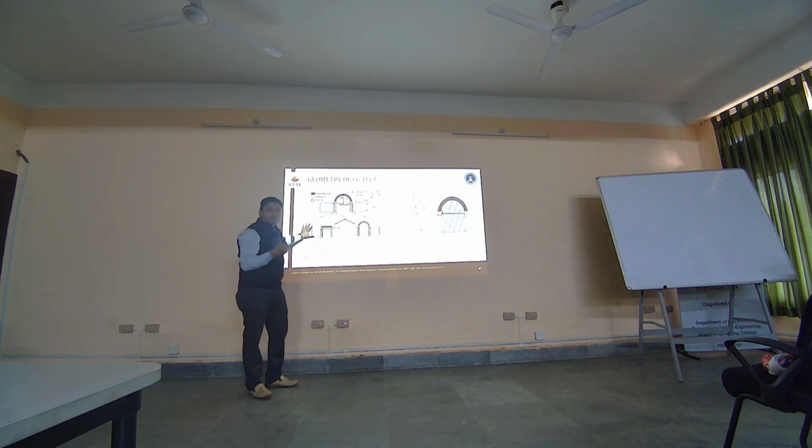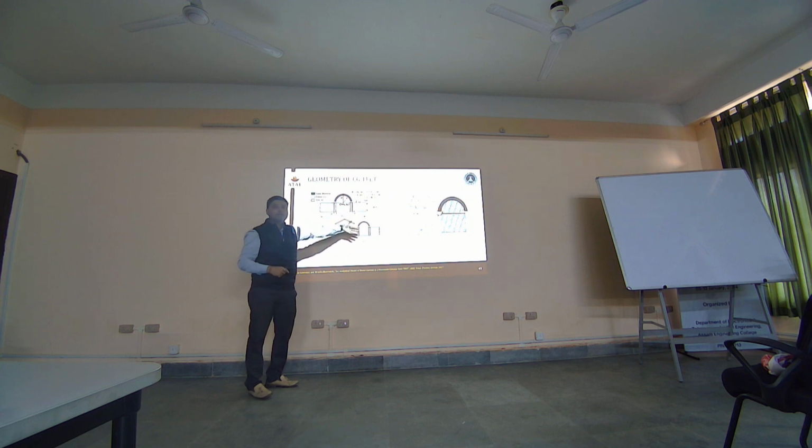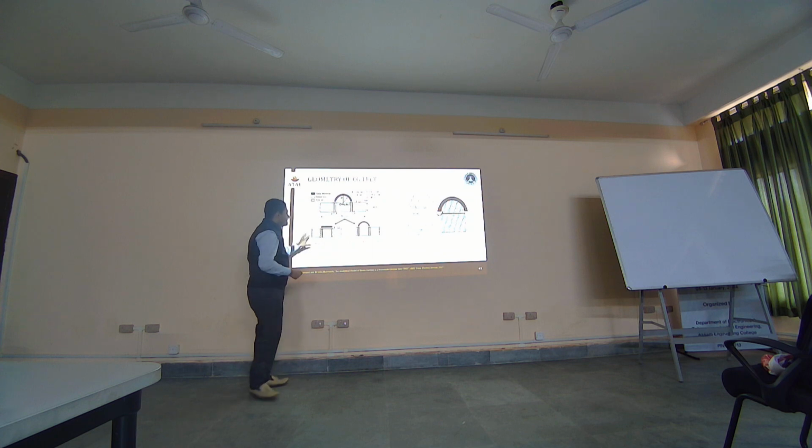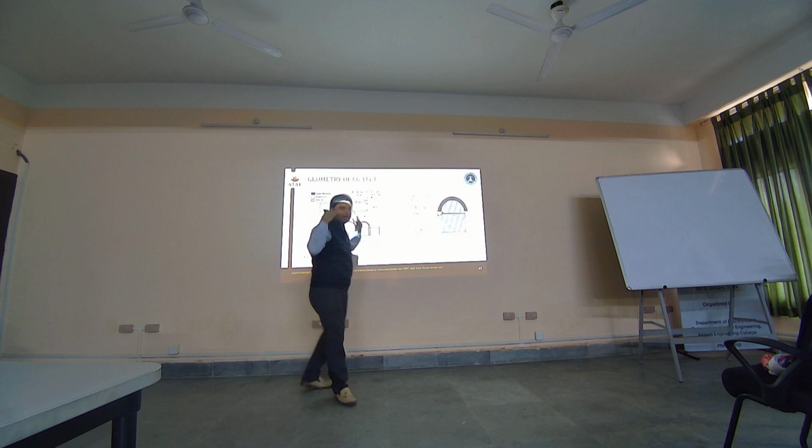Now when we start with rectangular structures, you have very set conditions. You start with the Poisson equation, then you apply your parabolic or quadratic approximation, then boundary conditions, then surface potential. Here you cannot do that. And if you do that, I am showing you what results you are going to get, and without doing that, by applying the technique which we use, what results you are going to get.